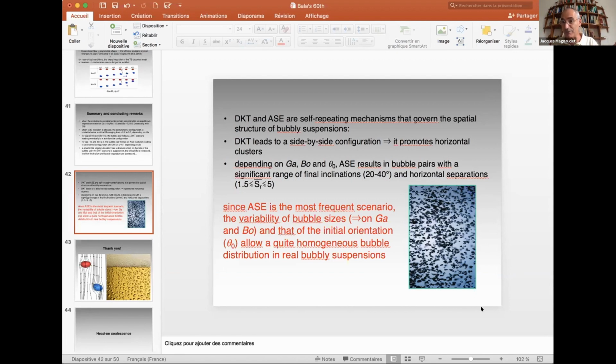Also, the hydrodynamic force in this case is attractive. So all forces are attractive. Unless there is a lateral deviation, all forces tend to make the two bubbles coalesce, and they will coalesce if we let the process evolve.